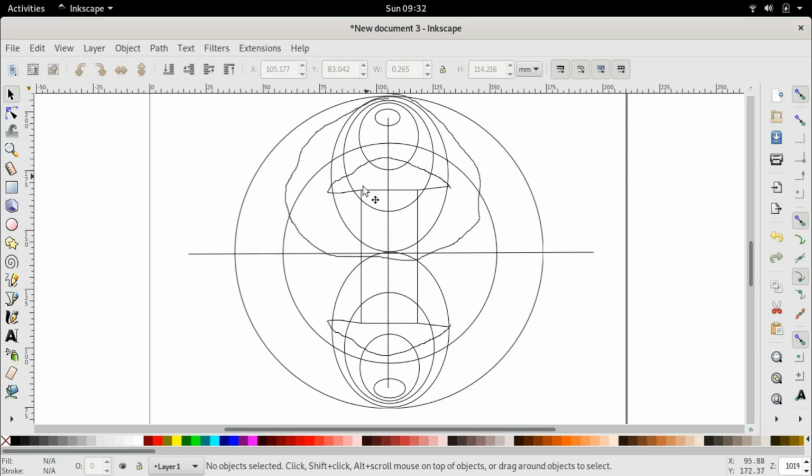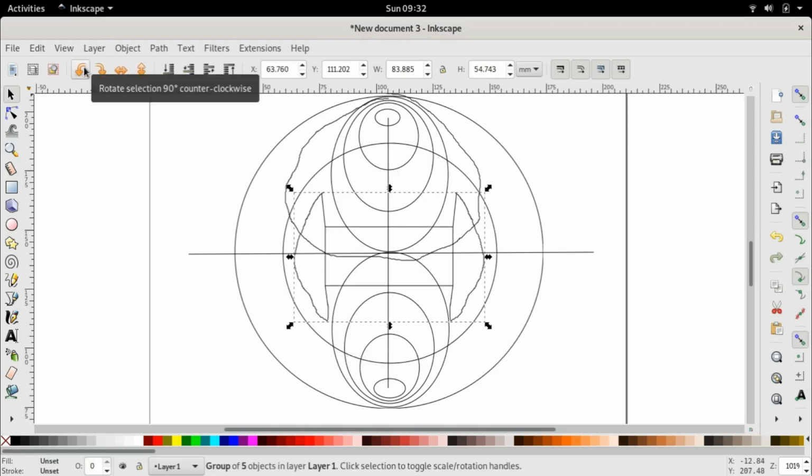So in this position, when the rotor is 90 degrees away from the horizontal axis and is aligned with these stator slots, it is very easy to see that the flux is much lesser. In comparison, if I rotate this rotor, in this position the flux is maximum.